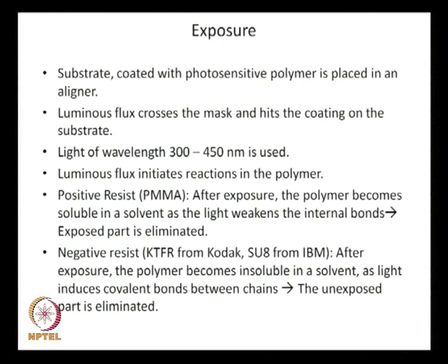The entire idea of spin coating is to make sure that there is a coverage of polymer over the entire substrate, and then it would be taken to the exposure step, where a part of the polymer will be exposed to light. So, one portion would be the lit portion, and the other portion would be the dark portion, and then depending on where it is lit or where it is dark, that polymer will be dissolved, will be taken away from the substrate.